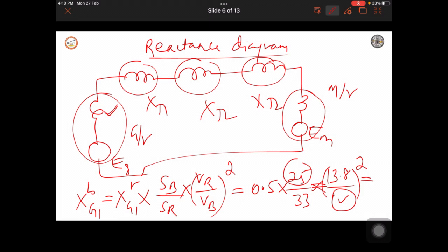Similarly, you can write the calculation for transformer 1, transformer 2 and the motor. Same formula we have to use, and base power remains always same, and rated value of that component we have to consider. Rated voltage we know, for generator one value will be there. For transformer there are two values of rated voltages on LV side and HV side.